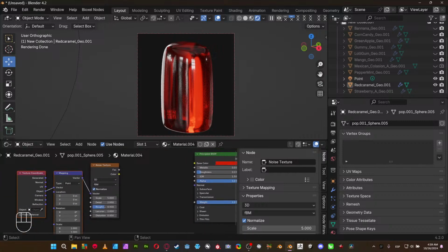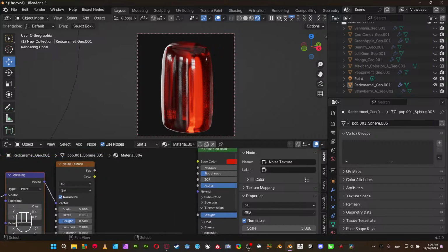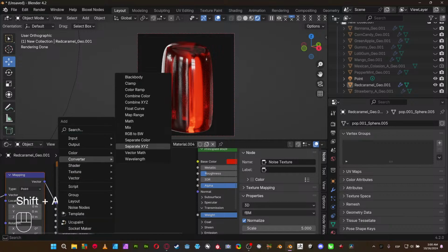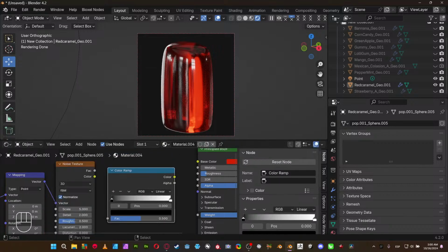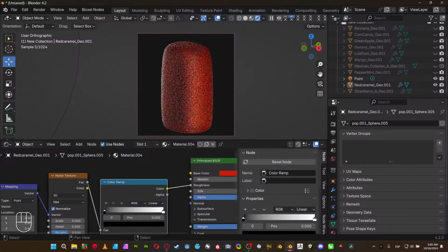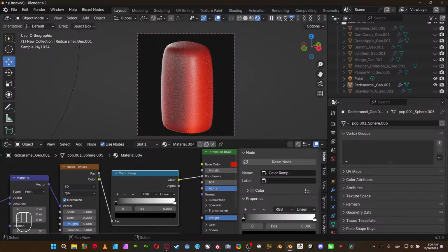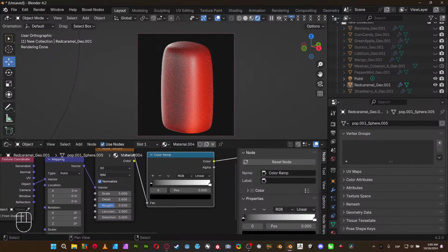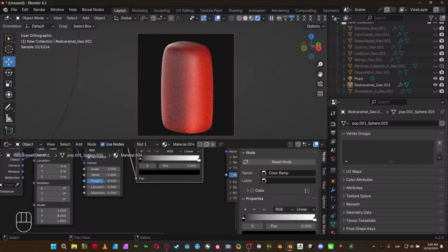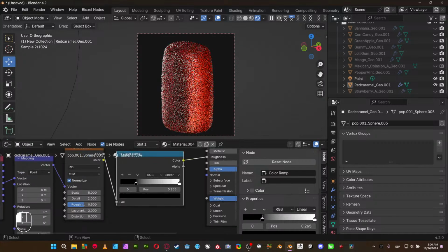We're gonna click object, we're gonna change it, and then we're gonna apply the color ramp. Then we're gonna click the factor in here. We're gonna connect it into the roughness, and then people are gonna tell me what is different. So let's just wait. We're gonna start increasing the value of one of these axes. Let's increase it to 8 in here, and then we're gonna start playing with this guy in here.